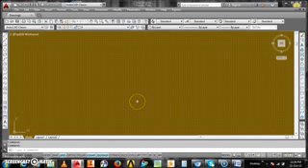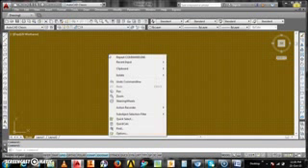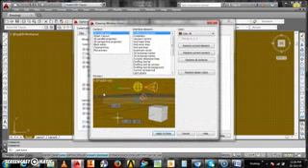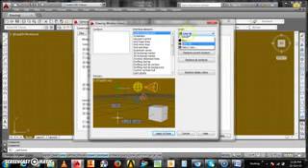First I will teach you how to change the display, because this is the most important factor. If you are working for long hours, you need a black display, because the lighter the display you select, the more stress it puts on your eyes. So just right click on this display, go to Options, ensure that the display is checked, then go to Colors, go to Uniform background, and select colors.